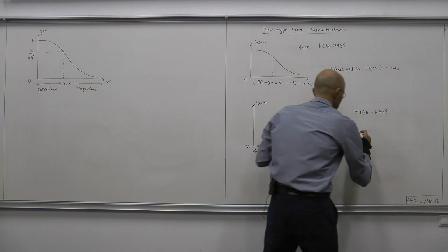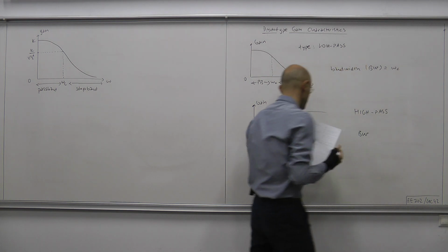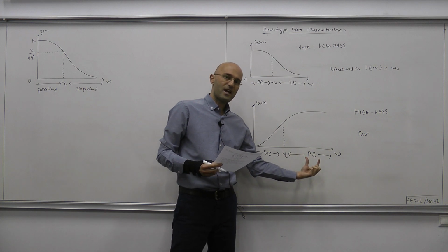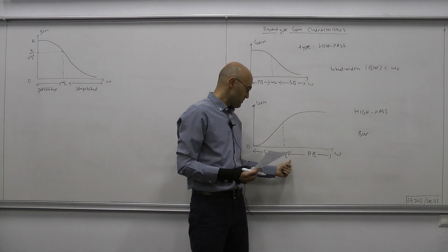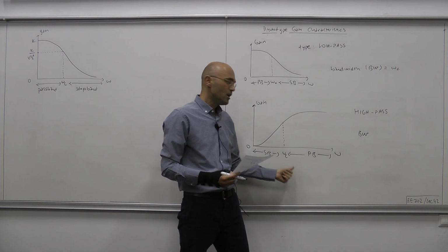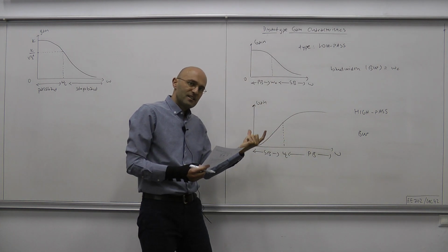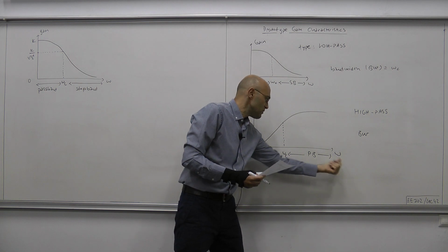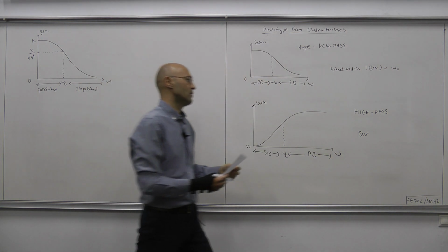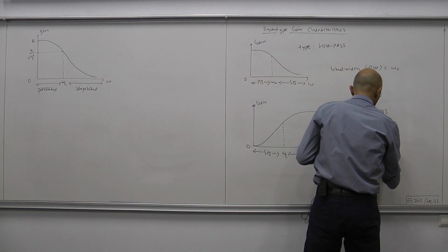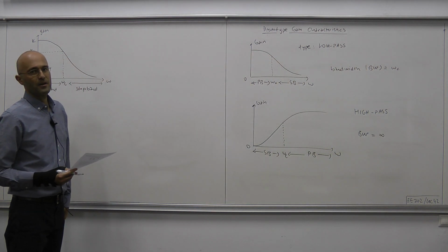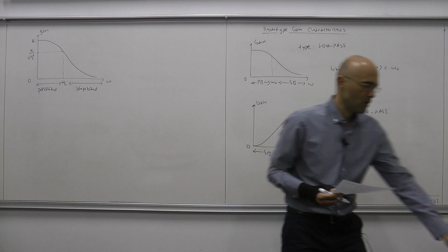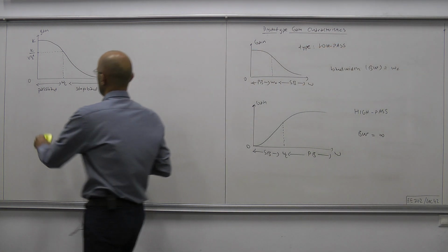Okay. As for the bandwidth, bandwidth is the length of the pass band. In this case, since the range is from omega c to infinity, the length of that interval is infinity minus omega c, which is infinity. Okay, so bandwidth is infinity.